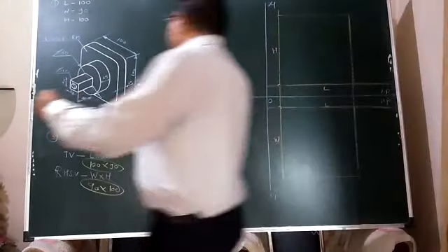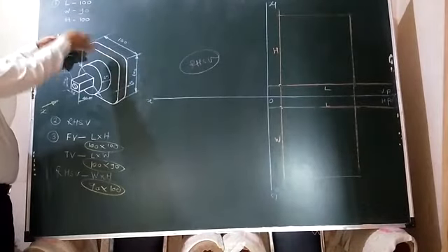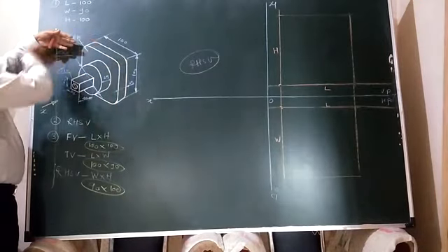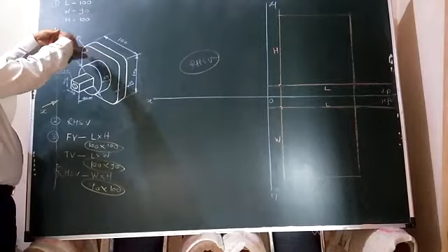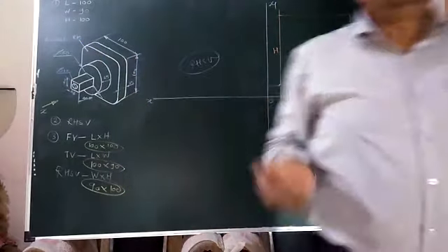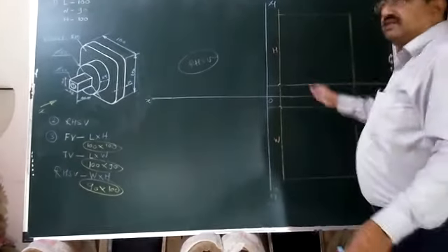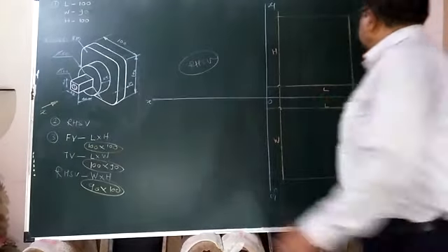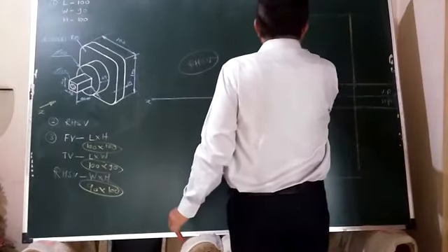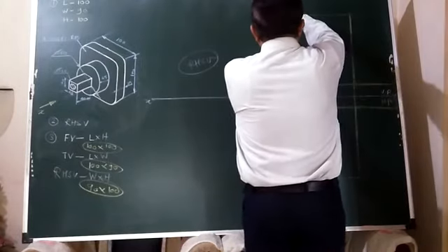And in the top view, now, when we observe from the top, okay, in this way only we should cut, that is vertically. When we observe from the top, the line of symmetry will be vertical. Horizontally we can't cut, because after cutting horizontally in the top view, it will not be converted into two identical halves. In the front view only it is possible to cut in this way centrally. In the top view only the vertical center line we should show. So accordingly, now you have to locate the midpoints here and construct both the center lines.